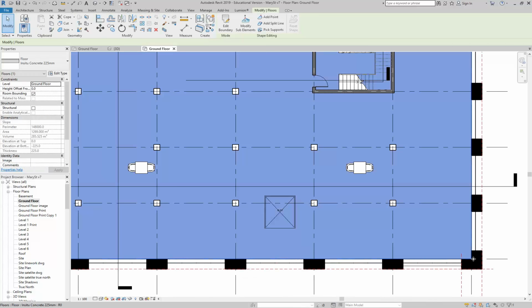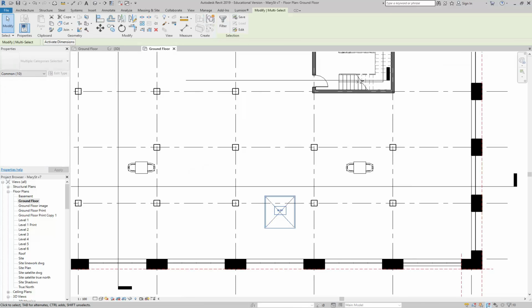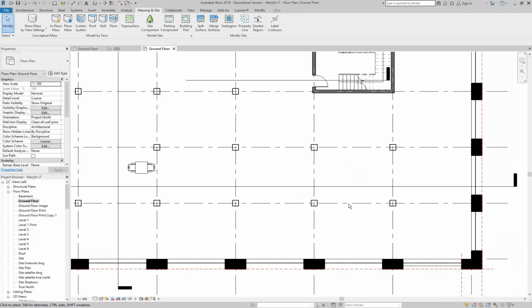Now another little tip there. If you're selecting lots of things with a window, turn off select by face. But make sure you do know about that option because it is really useful to have on sometimes as well. So you're often going to be toggling that on and off if you haven't used it very much.